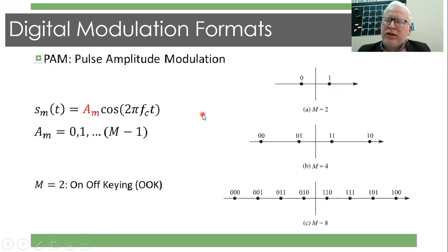Generally, we can represent any modulation technique, again, here I mean digital modulation technique, by what's called the constellation diagram. The constellation diagram simply is a polar plot that describes the amplitude and the phase of any symbol you are modulating. So, whenever you are considering a constellation diagram, you are considering a certain frequency, as the frequency is not observed in the constellation diagram.